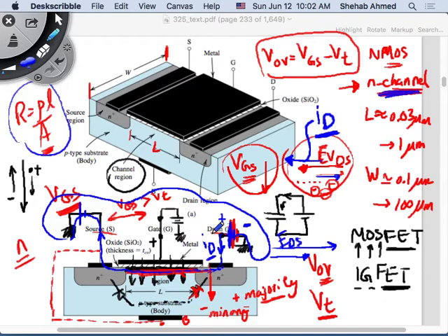Because we're going to get something interesting if you try to do that. This diode, we have a section called the body diode. This diode will start doing something interesting in that case, because if you put a negative here, then this is the most negative potential in the circuit, and this becomes positive, and this diode can conduct. Right now, if this is a ground and this is a ground, they're connected, this diode is forward biased or reverse biased? Reverse biased. It's in a steady state condition where I have 0 volts across it, so it's not forward biased.